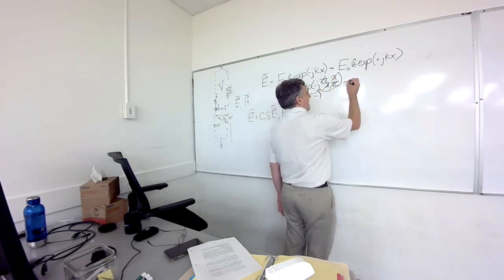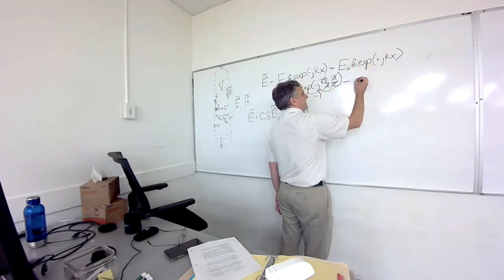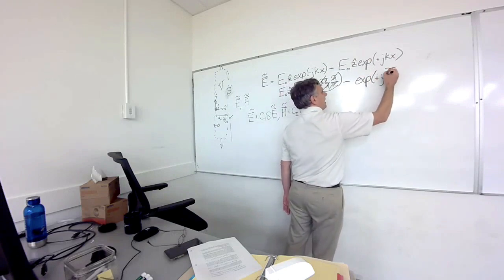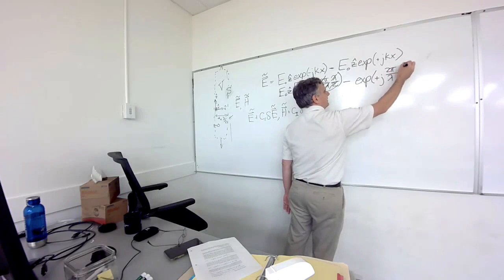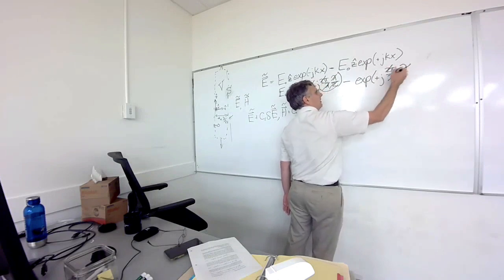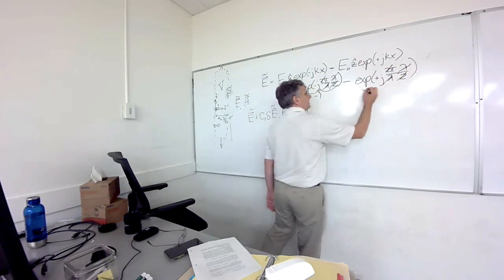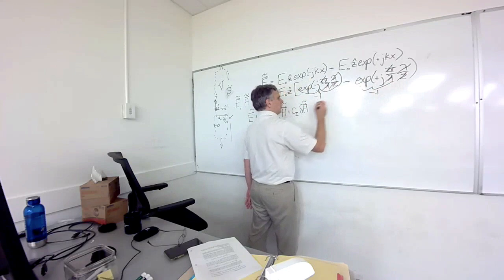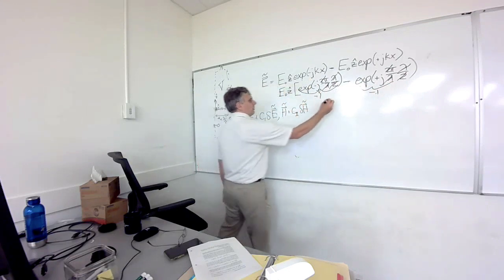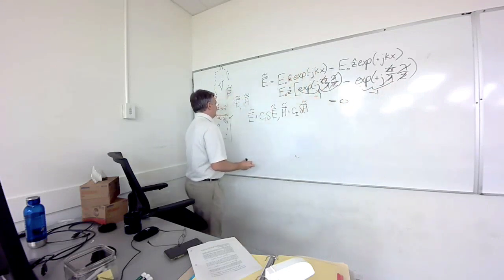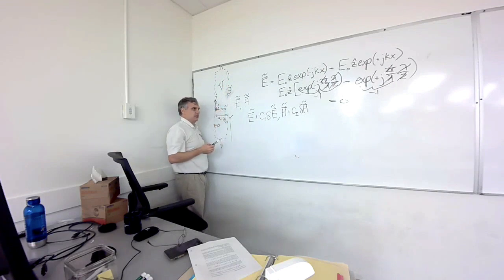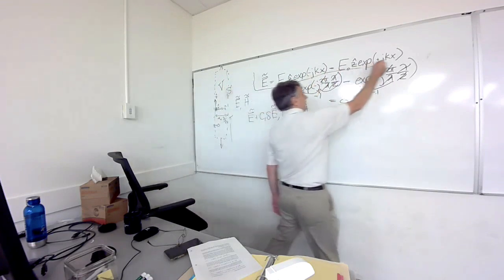Now I go over here, I have minus my exp, the same basic deal, j 2 pi over lambda times lambda over 2. The 2's cancel, the lambdas cancel. This is also going to be minus 1. Minus 1 minus a minus 1 is also 0. So all along this x equals lambda over 2 surface, my field is going to be 0. This satisfies Maxwell's equations.